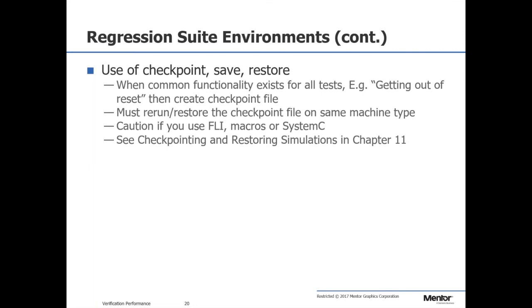So checkpoint and restore, the easiest use of it is for disaster recovery. If you've got a simulation that runs 5 days, you probably want to checkpoint it every 4 hours or so and create a checkpoint. And what that does for you is if 3 days into your 5-day simulation, you have a thunderstorm and the power goes out, you can restore the last checkpoint, restart your simulation from that point, and only need to simulate for 2 more days. So that's the easy way to use this.